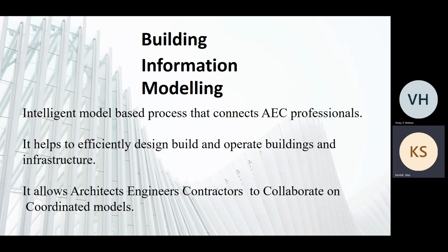In a typical scenario, what happens is both the team from structural engineering and the HVAC unit have to sit together and solve it on the site, right? But with Revit, what happens is we do something called clash detection. Once the modeling is done by both the structural engineers and the HVAC engineers, these models will be checked against each other, and they'll find clashes.